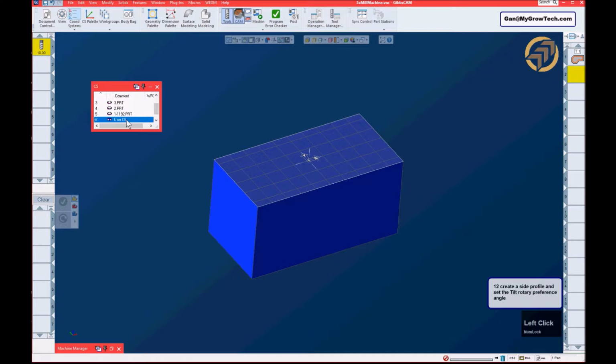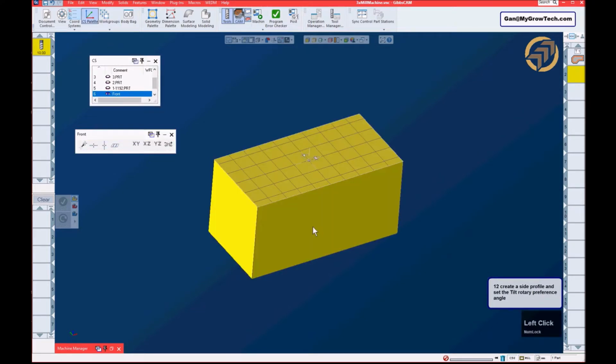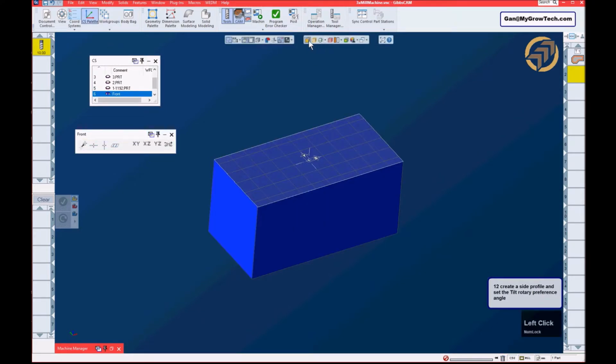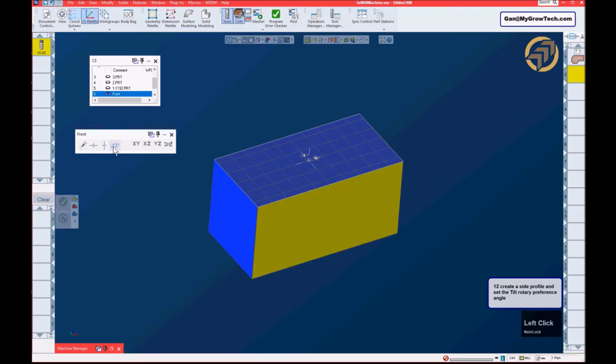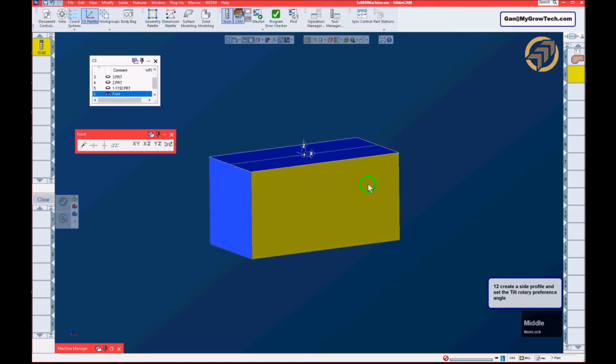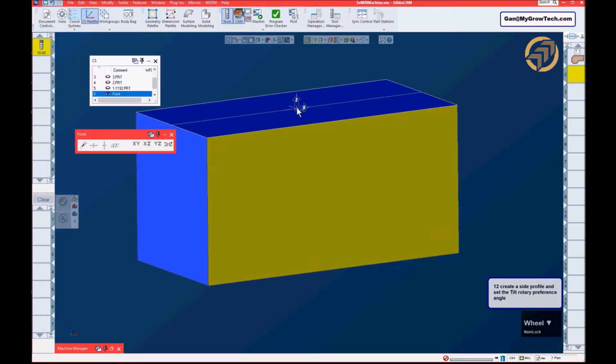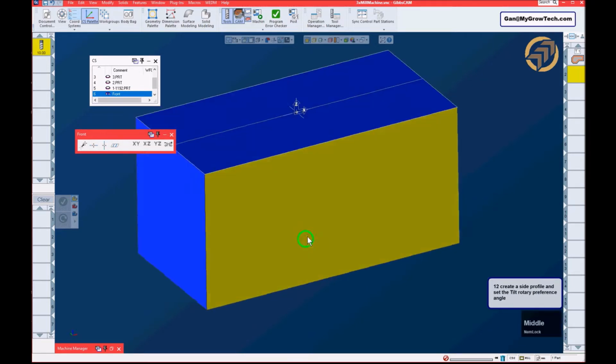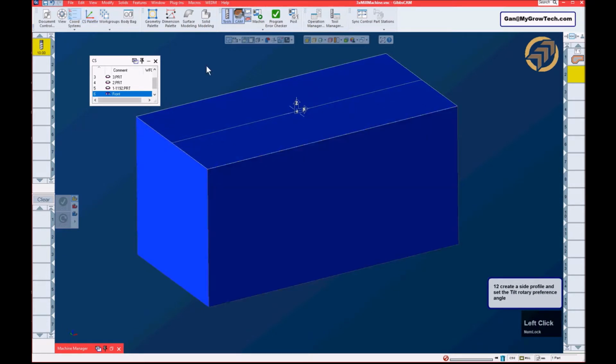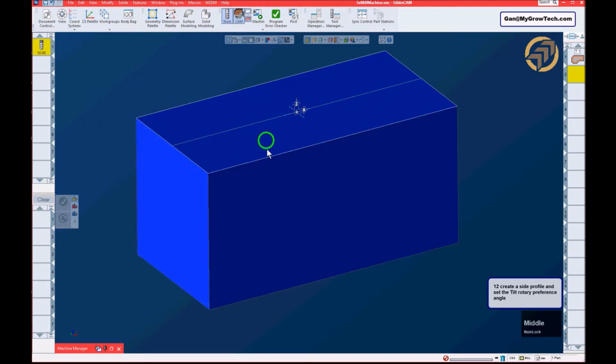Let's say we put front, and I'm going to modify this CS by the CS palette. Just choose this face, and you can see that plus means that my cutter is coming from the front. Yeah, so this is what we want, and we're going to do some machining.